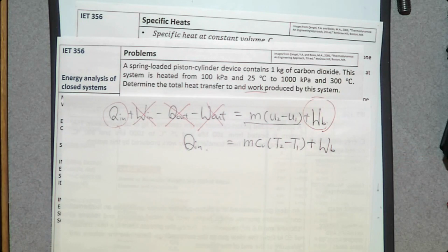So whenever you have a thermodynamic problem, always the first thing you need to do is ask, is there phase change or not? When there's a phase change, you need to use a steam table as we did in the previous problem. But if you assume there is no phase change, it's simple as this: specific heat.